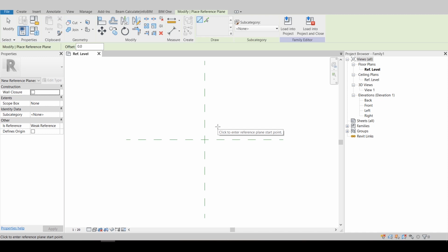For example, we create the cube with three parameters. There are width, depth and height. Accordingly, if we want to create the width parameter and want the family to change it to the both sides evenly, we are placing the two planes on the right and left sides. And if we want to change the depth on the one side, maybe the northern one, we create one plane.